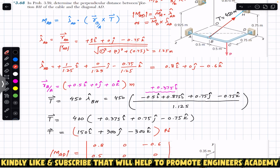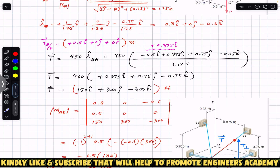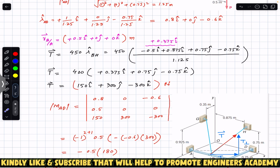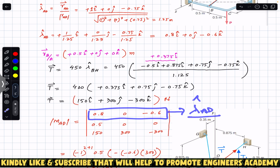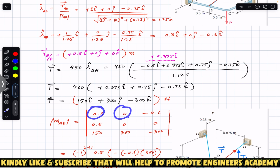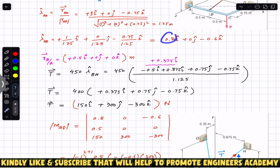Now, once we find these three, the unit vector from A to D, the position vector of B relative to A, and the Cartesian vector representation of that T, then we need to write them in a determinant of a 3 by 3 matrix. The first row represents the unit vector from A to D, and each element of the matrix represents the component of those unit vectors. So this is 0.80, 0, minus 0.6.